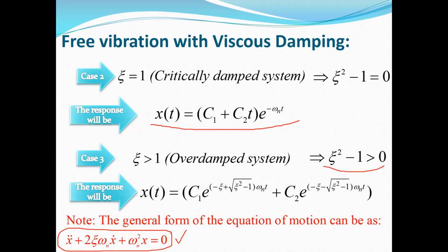Then, when the coefficient of x double dot is equal to 1, the coefficient of x is the natural frequency squared. I mean, the square root of the coefficient of x is the natural frequency of your system. And then you can obtain the damping ratio, psi, by using the coefficient of x dot.